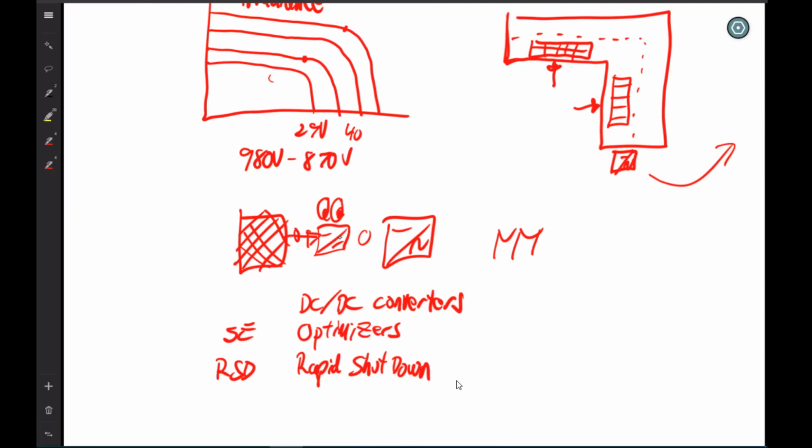What you do is you attach these rapid shutdown devices just like a microinverter. I said that microinverters were the size of a book and mounted right to the back of the module. Same thing for these rapid shutdown devices. They're very small, right to the back of the module. So basically it stops the power from going through your house or your commercial building. When the fire department wants to shut power off, they can, and it increases the safety immensely. So that's a rapid shutdown device.